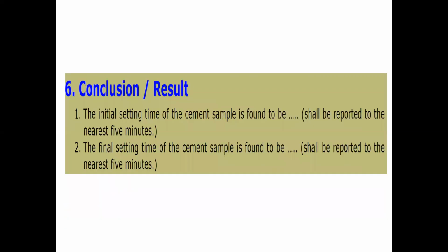And for our conclusion or result, the initial setting time of the cement sample is found to be, shall be reported to the nearest 5 minutes. The final setting time of the cement sample is found to be, shall be reported to the nearest 5 minutes.